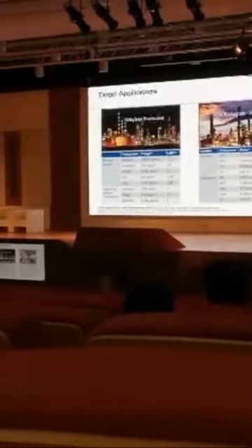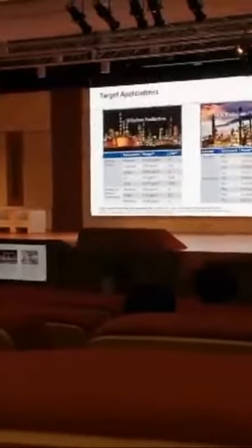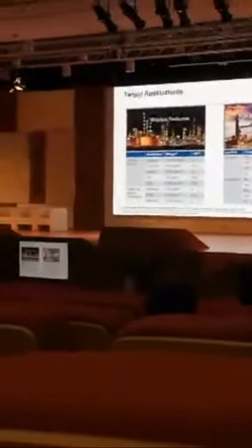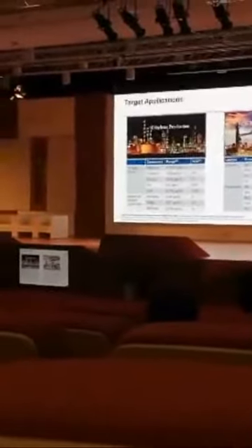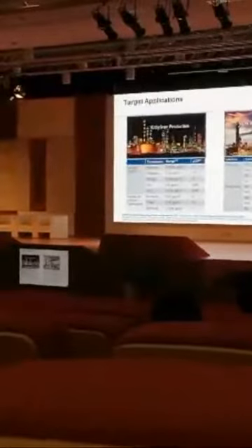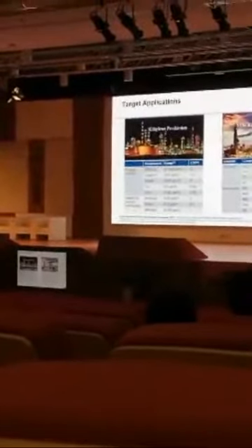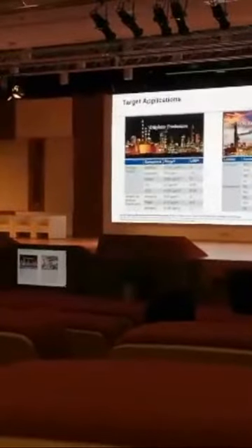This is quite a useful tool, because normally in a stack emission you would have very low levels of NO2 in comparison to the nitric oxide levels. The same goes with the downstream measurements. You can see that the limit of detection is quite good, in the low ppm levels. The ranges are indicative. We can go to lower levels. We can in fact go to higher levels as well.